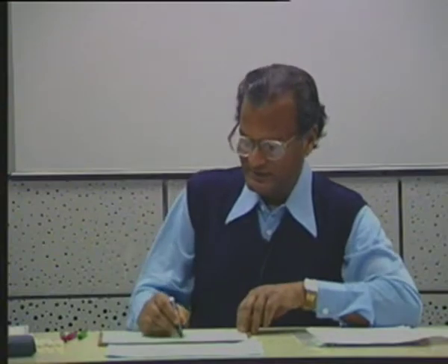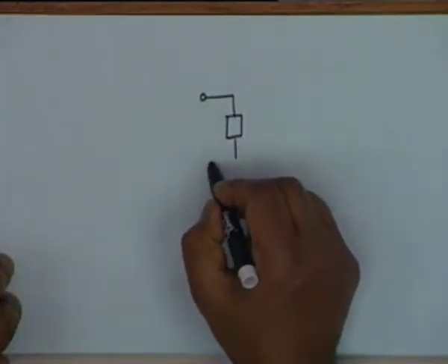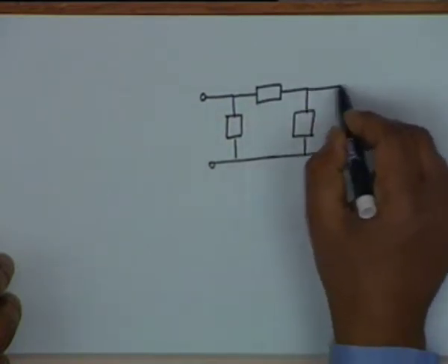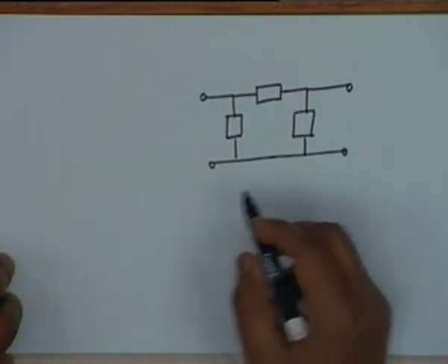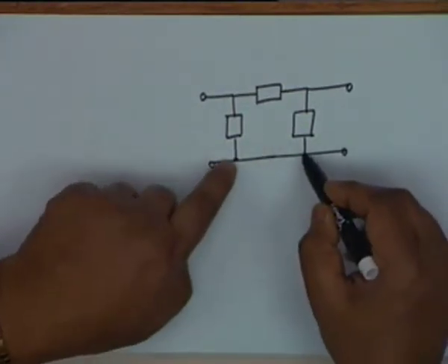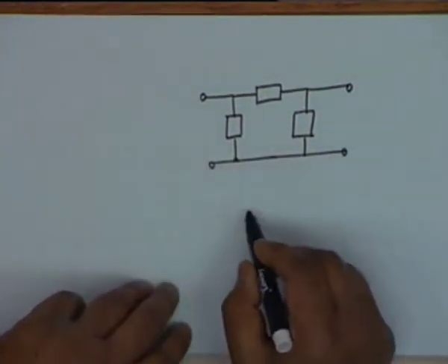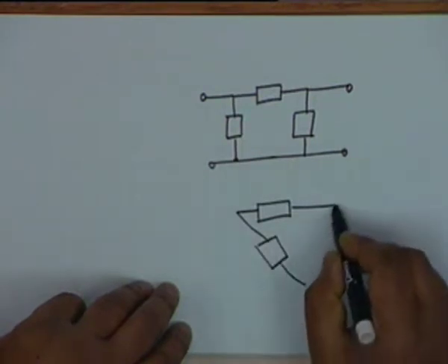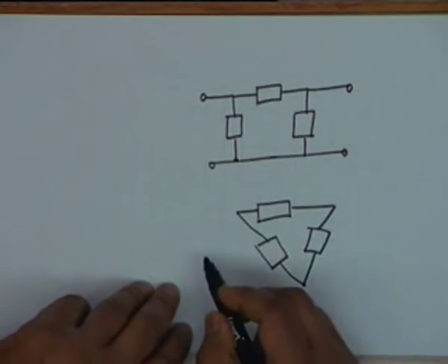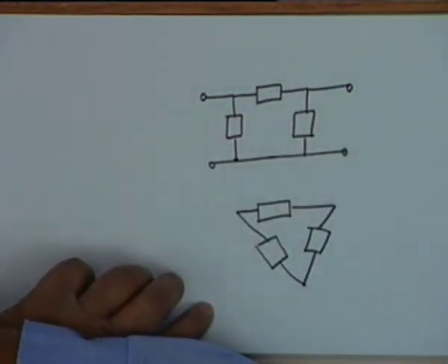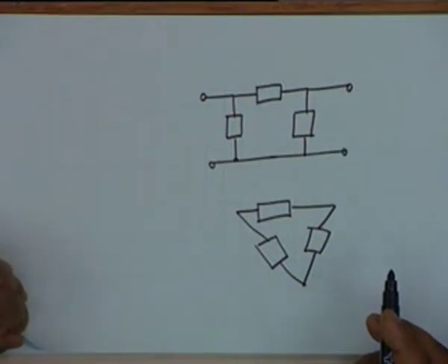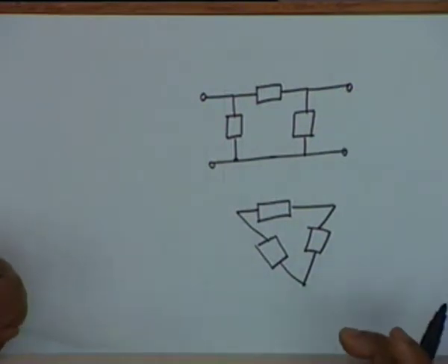This pi network which we have just drawn is the short circuit Y parameter equivalent model of the equations. Well, if you pull these two terminals close together, then another way of representing this network is a delta. This looks like a delta, and therefore this is also called the delta network model. Instead of pi, it is also called a delta network model of the two simultaneous equations.